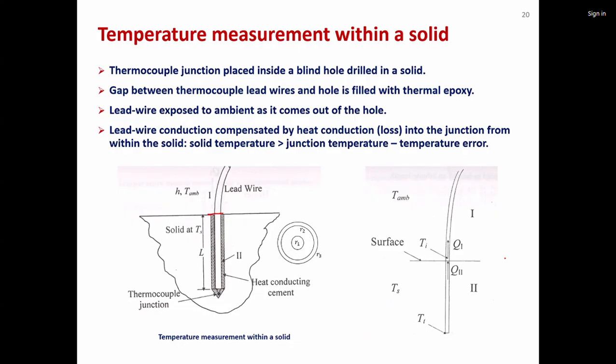So now, for heat transfer analysis, the first segment here, region 1, is similar to the previous example that we have taken. In that case, we had the temperature of the tip, but here it is the temperature of the interface. This is a wire which has a tip temperature of Ti, and this fin is infinite, exactly how we analyzed the previous example.